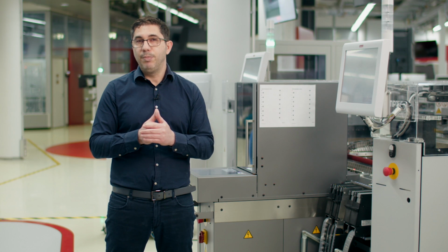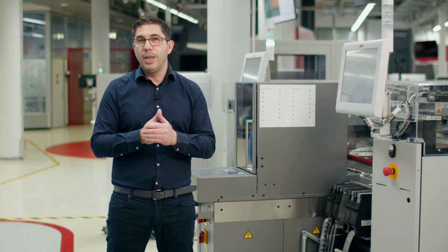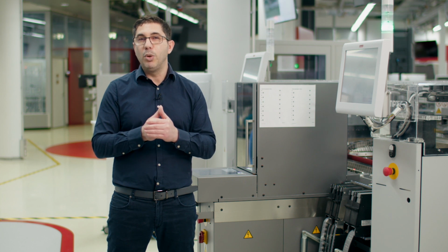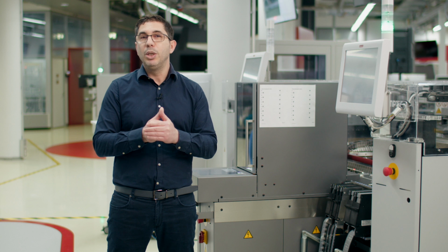Maximum feeder space. Since the components might be very big, they might also occupy a lot of feeder slots. A head which is capable of handling all these different components, all these big, heavy, and tall components. And a head which is capable of applying different placement forces and still being very accurate. A machine which is capable of handling different packages like trays, sticks, and tubes.